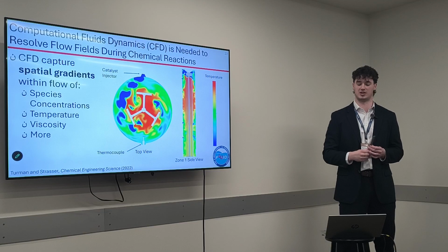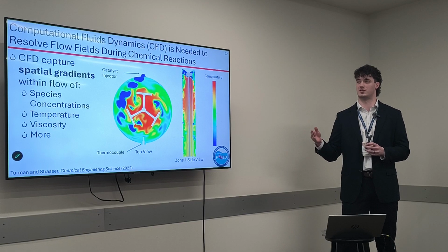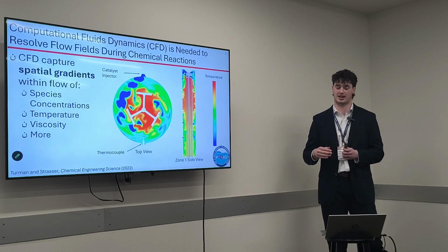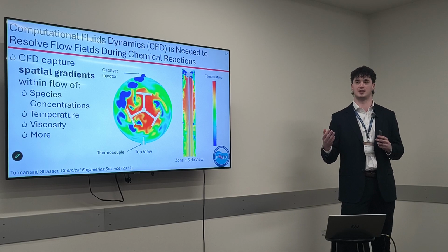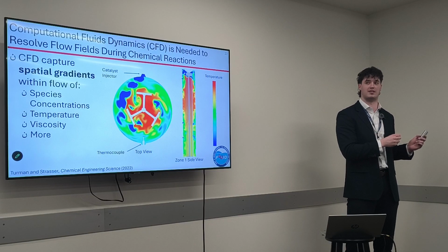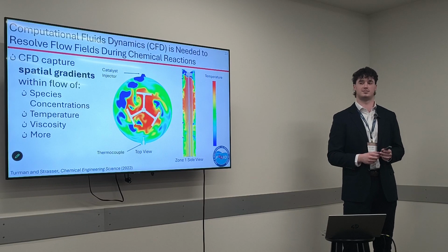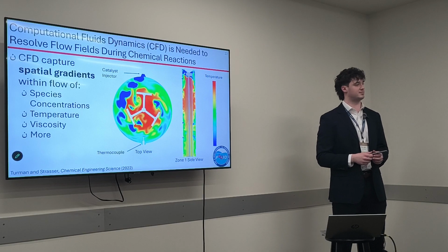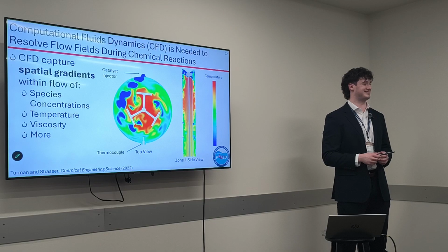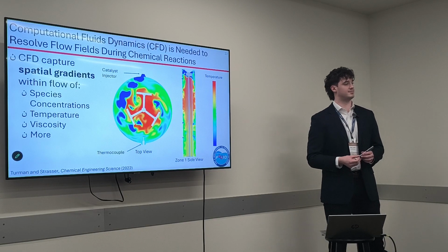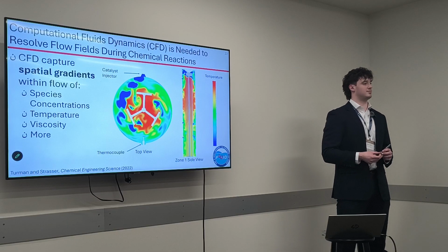I suppose in a simulation with the frozen flow field and a converged flow field that isn't really changing anymore, QSS, we're kind of assuming that hotspots wouldn't form in that flow field already. Really, what we're doing, as far as I understand, is that you're still allowing convective cooling by freezing the flow field.